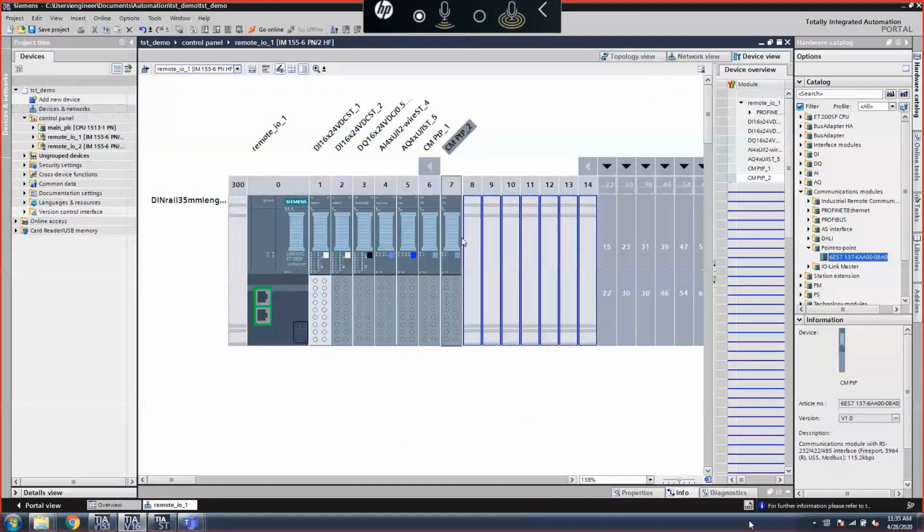Now, if the PLC programmer wants to give this information back to the designer, so that later on when he does the TIA selection tool design for a later project with a similar architecture, what the programmer can do is, instead of telling him, okay, add 2 communication modules, he can really do the reverse task. He can export the data from here as an AML file, and he can transfer the AML file to the designer, who can import it back in the TIA solution.